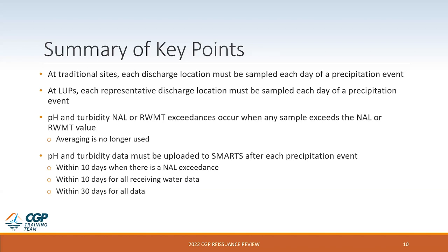NAL exceedances are reported by uploading and certifying the data in SMARTS within 10 days of the completion of the event. Receiving water data is also reported by uploading and certifying the data in SMARTS within 10 days of completion of the precipitation event. And all data, regardless of whether it's exceeded an action level or not, must be reported by uploading and certifying the data in SMARTS within 30 days of the completion of the precipitation event.